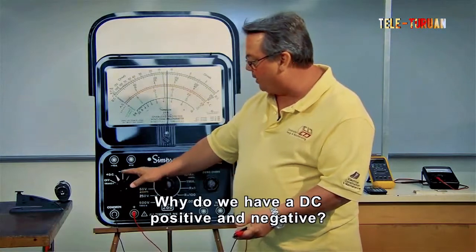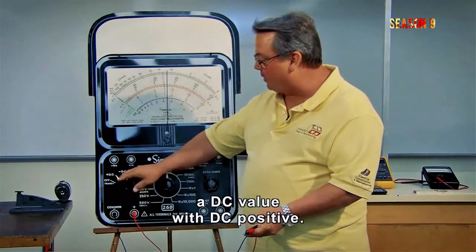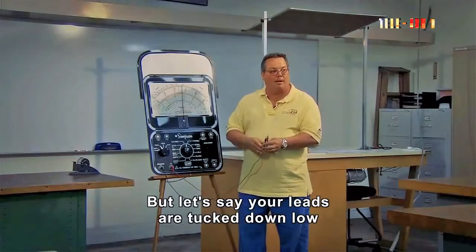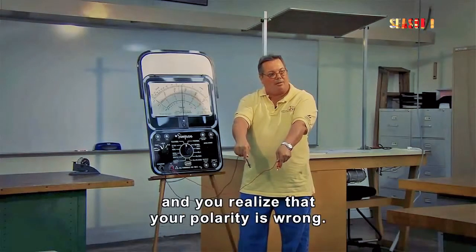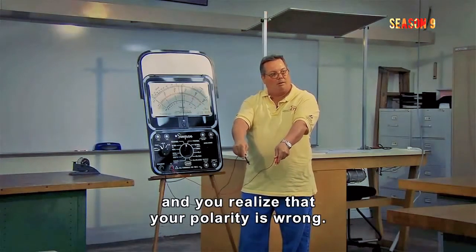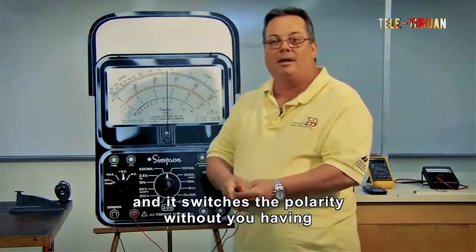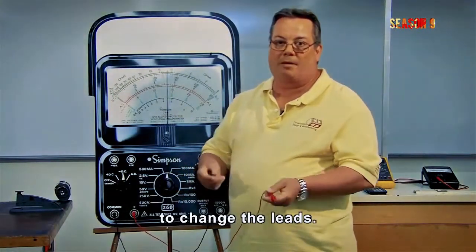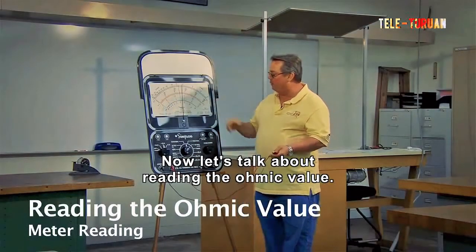Why do we have a DC positive and negative? Well, we set up our meter to read a DC value with DC positive. But let's say your leads are tucked down low where you can't get to them easily enough, and you realize that your polarity is wrong. To change that, you just go to DC negative, and it switches the polarity without you having to change the leads.